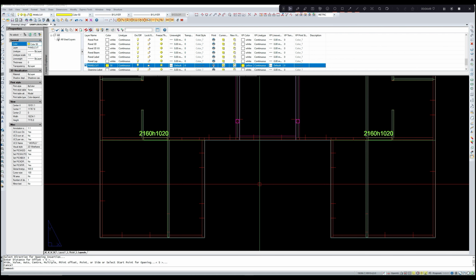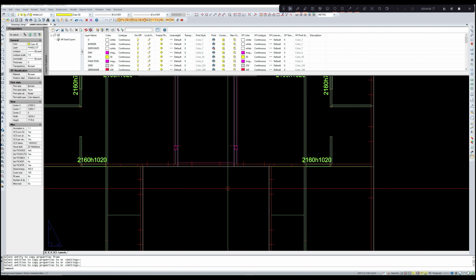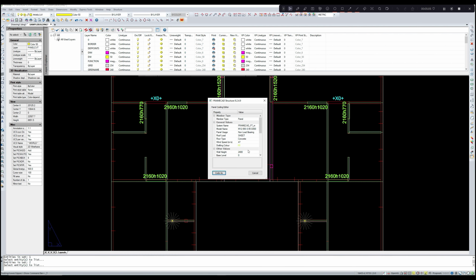We had missed one of the walls between the two bathrooms. Let us create that. The wall should be created by creating a line first. List this wall as a non-load bearing wall. Wall height is 3050.